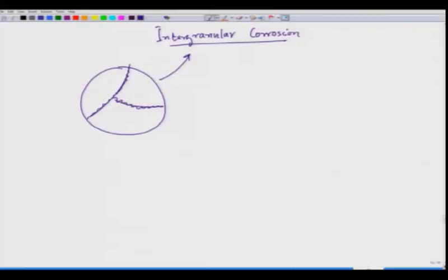The classic example is 18-8 stainless steel. 18%, which is weight percent, is chromium and 8% nickel. When we have 8% nickel, the structure becomes austenitic stainless steel, and this austenitic stainless steel can be made at a very low carbon content or moderately high carbon content.